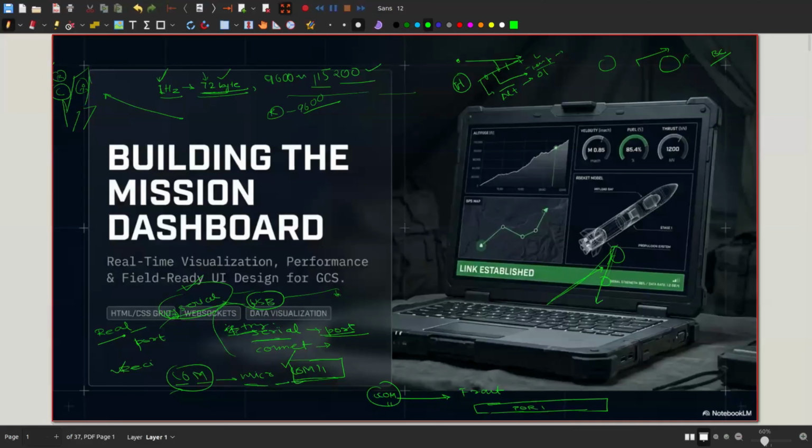This is the port R. And again, this is a drop down option, it has different values. Let's assume 9600, and that's called baud rate. In this scenario, what happens is the backend forwards this port, the port R, and in the drop-down option, you can see that there is COM11 connected.